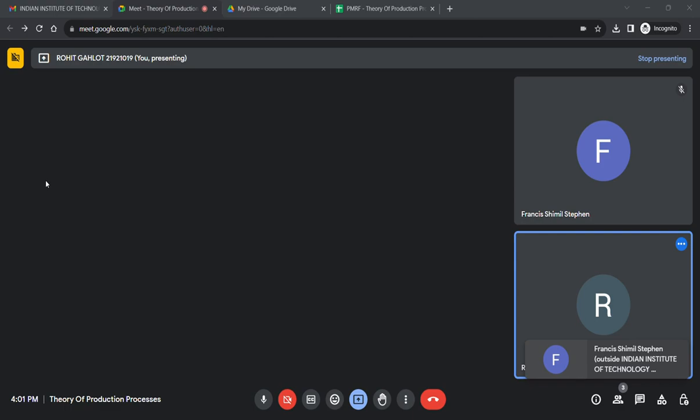But generally, we will be using a cylinder. Any type of riser you can use. Some people also use trapezoidal, some use a taper, some use cubical. N number of types of riser can be used. But generally, to keep the problem simple, it is written to use the cylindrical side riser or top riser. So we have H equal to D and V by A equal to D by 6 only for the cylindrical riser.